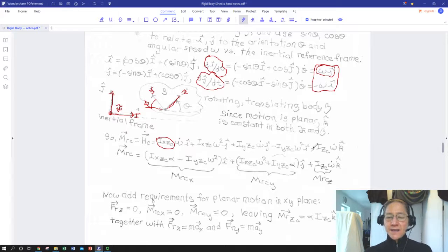in the YZ. And then the polar moment of inertia, the one that is with respect to the z-axis pointing out of the plane of motion, we didn't have to do any kind of crazy transform of the unit vector because, again, little k hat is the same as big K hat from the inertial reference frame, so it just ended up being our same polar moment of inertia times the first time derivative of the rigid body's angular velocity, omega hat.